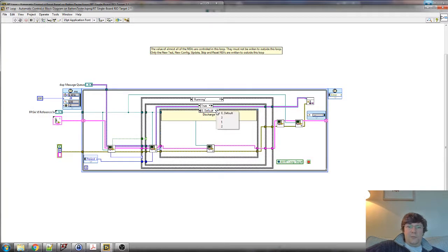And if it is, we might be discharging, we might be resting, might be charging, or we might be running a profile, which could be a voltage profile or a current profile, even a power profile. The control method and the fact that we're in a particular mode of operation, they're not linked together. Of course, if you're resting, the contactors are open, you can have a hard time getting anything to happen besides watching the voltages.